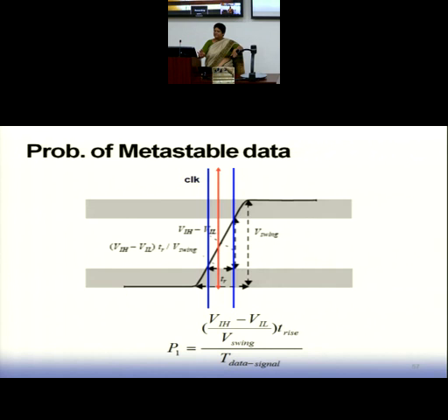It is completely 0 here. It is completely 1 here. Okay? If it is sampled here, it doesn't matter. Only if it is sampled between VIH and VIL, there would be metastability happening. Accordingly, he computes the metastability range. So it is this duration, out of the complete T cycle of my data signal.